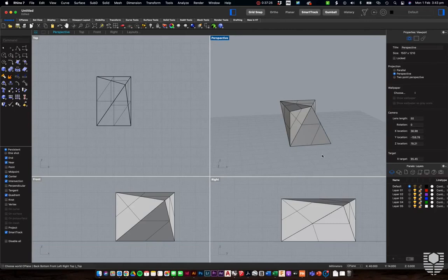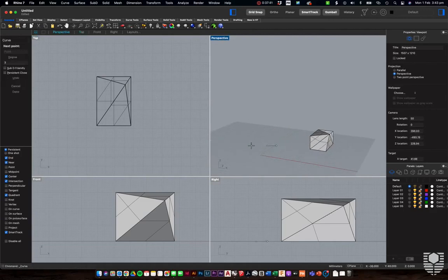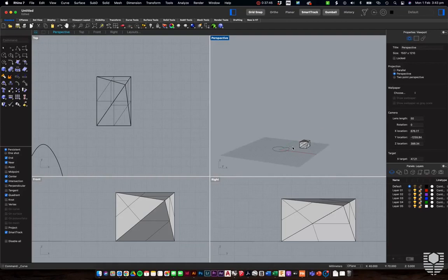All right, let's talk about another thing that's going to impact your workflow and make your life a bit easier. So you'll notice that when we're drawing, we're always drawing on this plane here, which is what we call the construction plane, and that is our sticky surface. If we grab a freehand tool, it's always going to stick down to exactly that plane. So if we now rotate around that, we can see that it's stuck down onto that construction plane inside there.